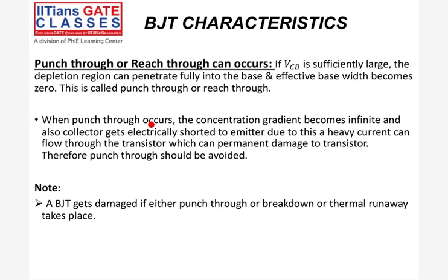So because of that, the base width is getting reduced to zero. This is called punch through or reach through. When punch through occurs, what will happen? The concentration gradient becomes infinite.